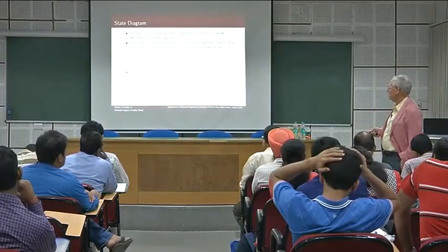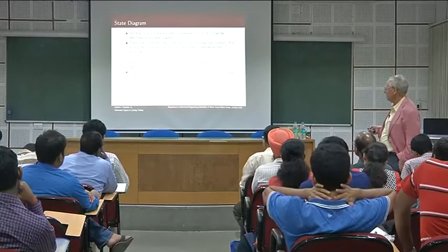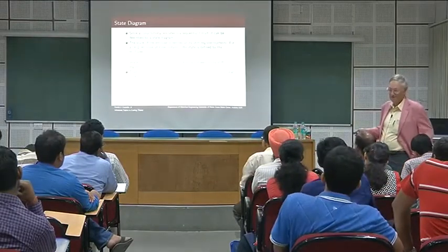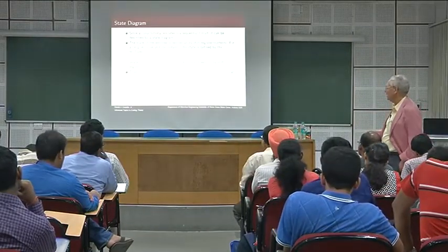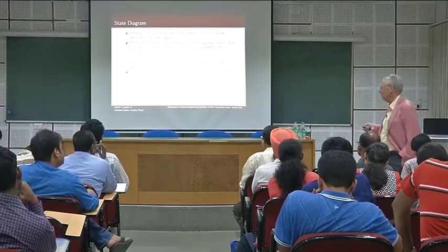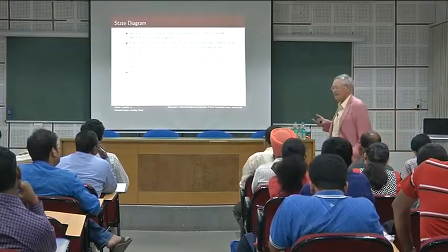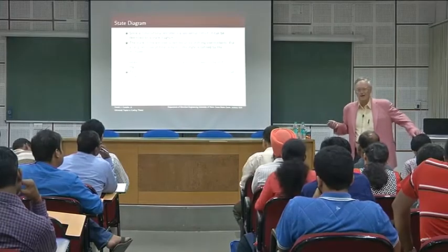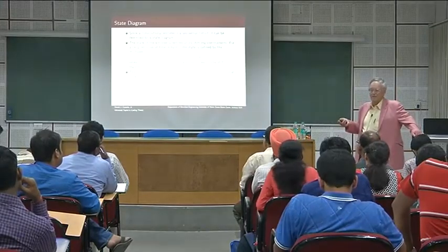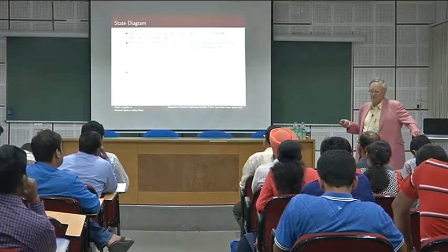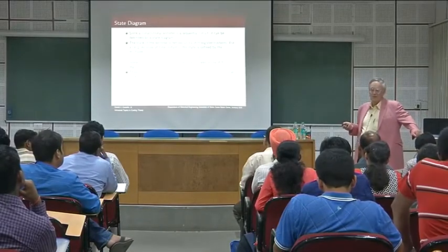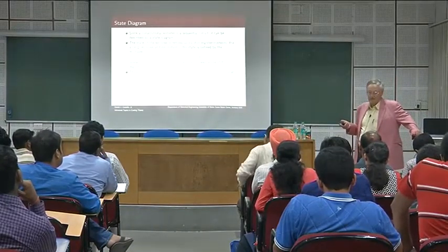And so there are 2 to the m possible states, because the state vector is of length m. Everything is binary. This is important because the complexity of decoding depends on the number of states. There's a maximum likelihood decoding method and a MAP decoding method.